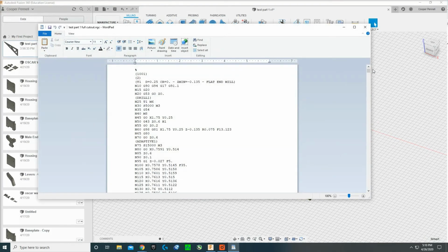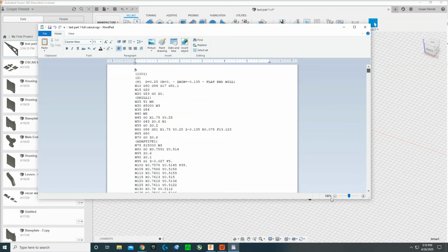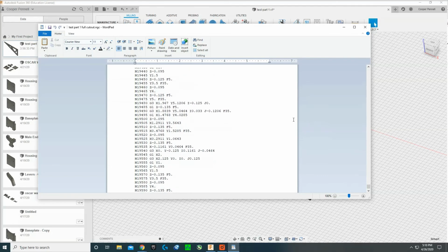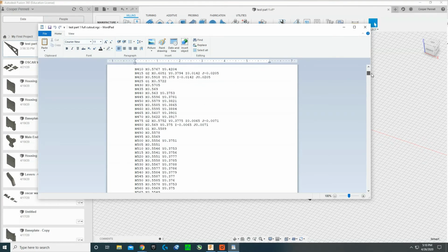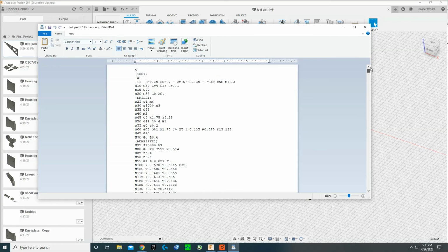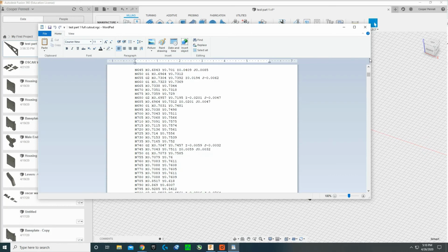And this is what the G-code is. You can see it's just a really long list of commands, 20,000 lines, I think I just saw, that are going to the machine. This all looks pretty good. You can see these are the I and J right here. These are the arc commands. If there are no I and J's, that means the smoothing commands that we put in for the 3D adaptive clearing and other stuff aren't going to be in there, and your hole is going to be off. But we have all that, which looks good.